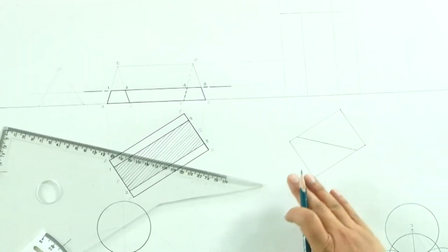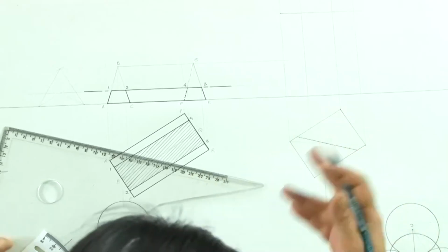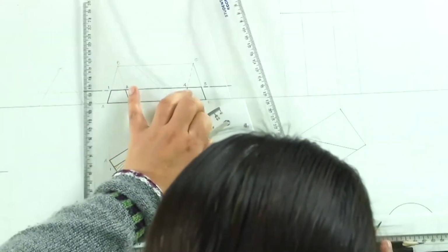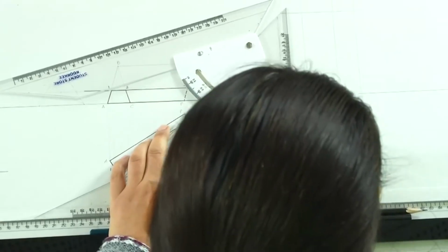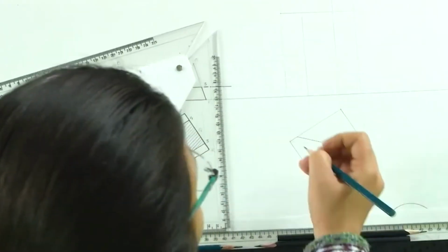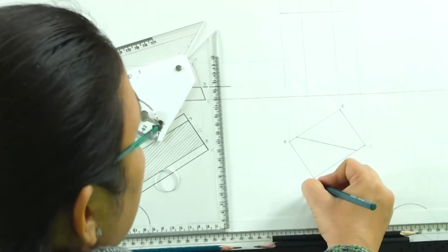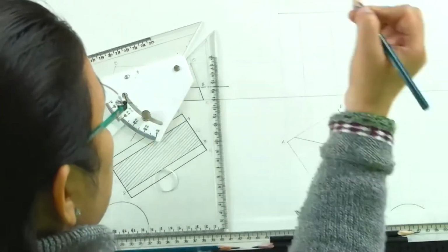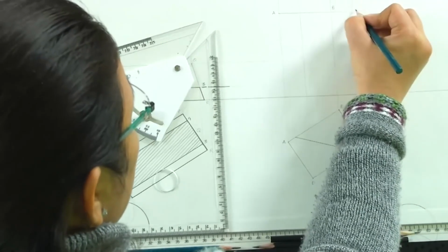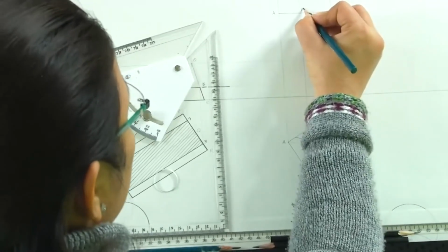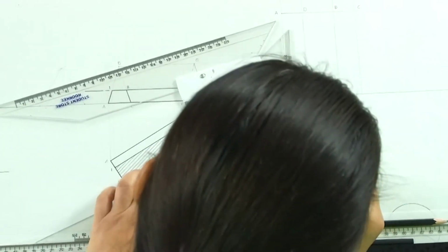So, we are assuming that this portion is now cut out of this solid. Let us take the projections back where this section line is cutting. Let us number it for our convenience. If this is A, B, C, D, I am only marking the top face, and this is A, B, C and D. Now, this AB is cut in this point.